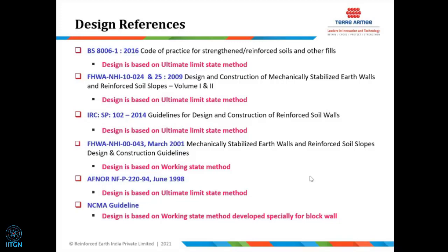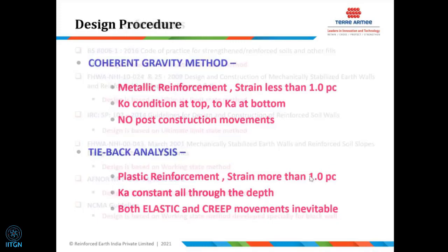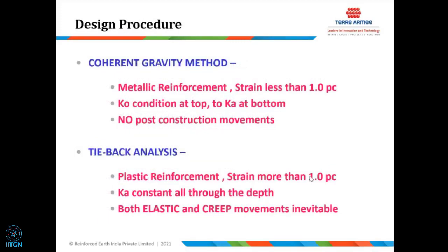But in India, these are the three main international ones, I would say: British, AASHTO, and AFNOR, that are acceptable. And in practice, it is only British and AFNOR. And of course, now the IRC, we are all following the IRC guideline. The concept is more or less the same. So the two design methods, which are well accepted internationally and in India as well, are the coherent gravity design method and the tieback wedge method.